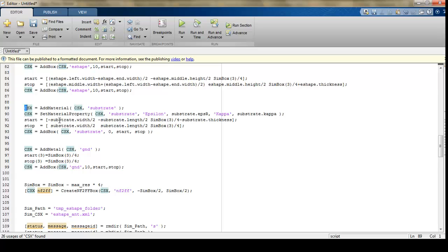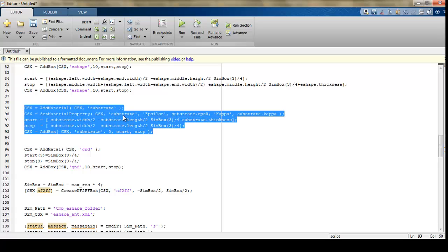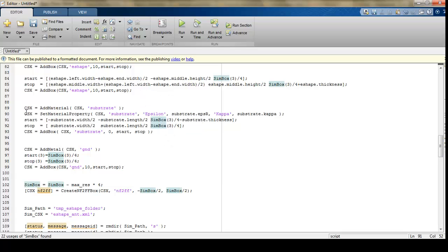The code defined here was used to add dielectric elements from our previously defined substrate properties. First, we create a basic substrate material using this line. We then give the created substrate our previously defined substrate properties. We now create a ground component using the same dimensions as the substrate defined above. This line creates a perfect electrical conductor. A ground 3D box model is then inputted as seen from this line.